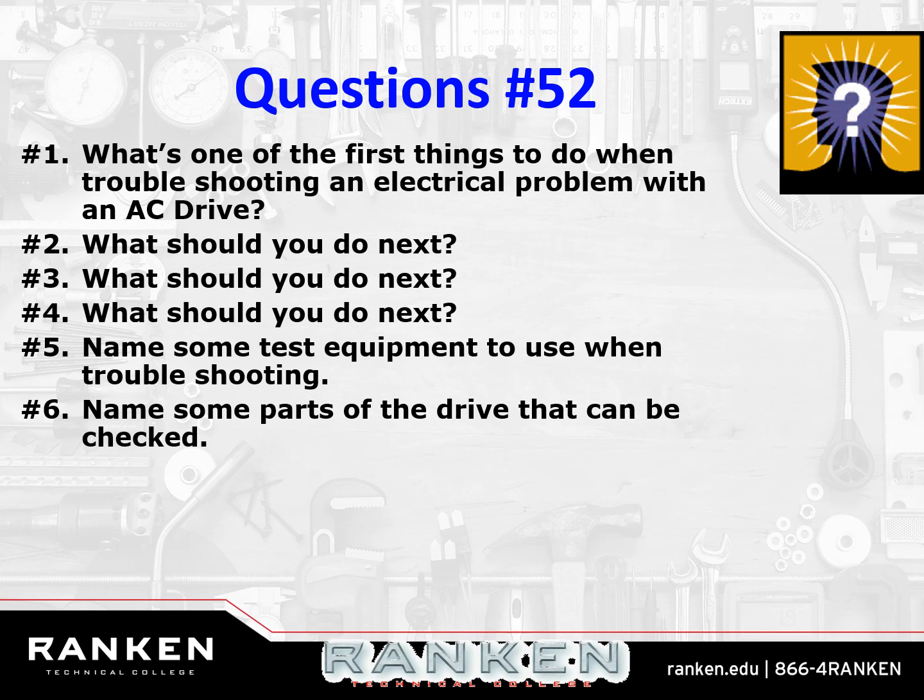Name some parts of the drive that can be checked. Well, there's a ton of parts on the drive that can be checked. You can check the DC bus, you can check the capacitors, you can check the diodes, you can check the IGBTs. You can check all that, but you have to take the drive apart to check it, and I don't know if you should be checking.